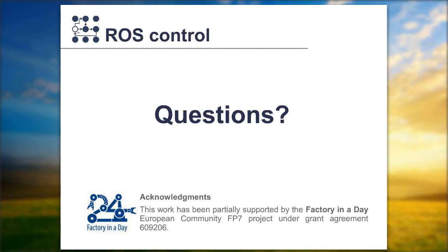But basically, what I would say is that right now in ROS, if you don't have real-time constraints, you can do a lot of things that you cannot do with ROS-Control. So things like expressing a computational graph, or chaining controllers, introspecting inputs and outputs between boxes in your computation graph. So there's many things that would be very interesting to do that the ROS-Control infrastructure doesn't really allow you to go further than a certain point. And what we're going to be talking about in ROS-Con is how the ROS2 project could help to make this happen.